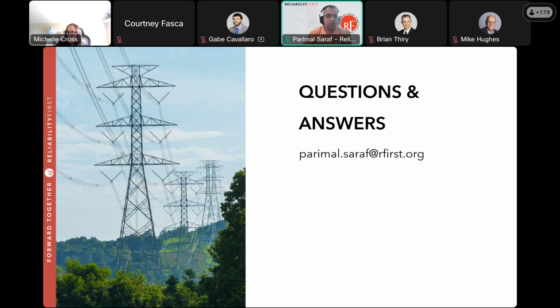Only in those specific scenarios are EMT studies being used right now. Obviously in smaller systems, like Australia and Chile, they have their detailed grid model in EMT, but they are smaller systems, so for them computation is not really that big of a challenge. But for our system, the Eastern Interconnect, it's not feasible as of now.